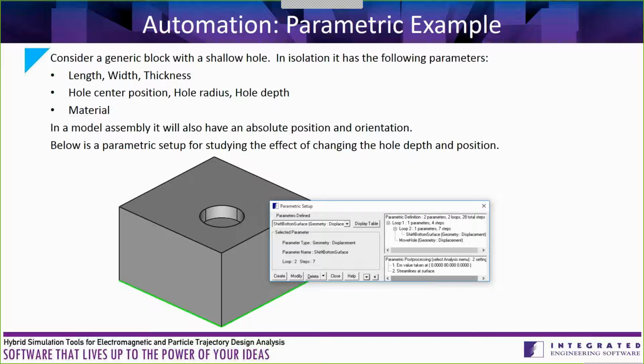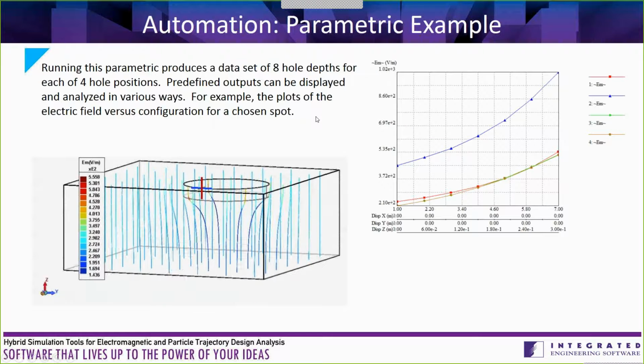Parametrics are a way that we have of automating when your model is defined and you simply want to run variations on the model. The new thing for us with parametrics, existing users will recognize we've been able to set up this kind of systematic study for many, many years, is that for this region, where I've defined what I want to get out of all the variations that are going to run on this model, there's a good argument for doing this part of it with the define outputs instead of defining it in the parametric itself.